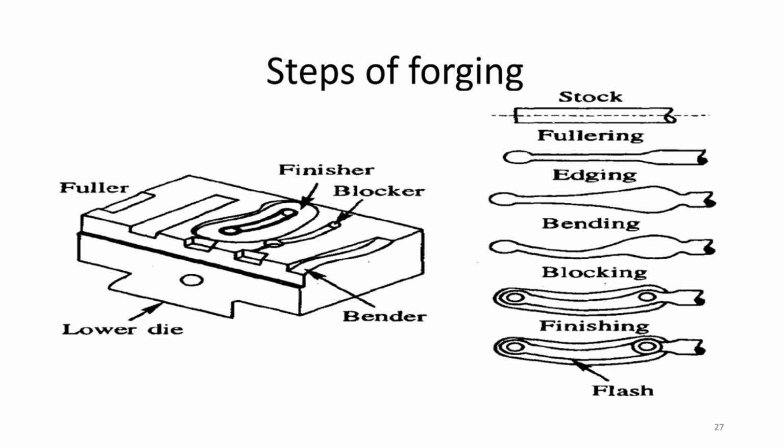After it has solidified and its temperature is reducing, that shrinkage will be dealt with by your pattern allowance. So in that case, you make your pattern a little bit bigger compared to what it should be. That allowance is always fixed, like how much you require in case of lead, or how much you require in case of aluminum. How much per meter of the casting is fixed. So according to that you provide pattern allowance for solid shrinkage.